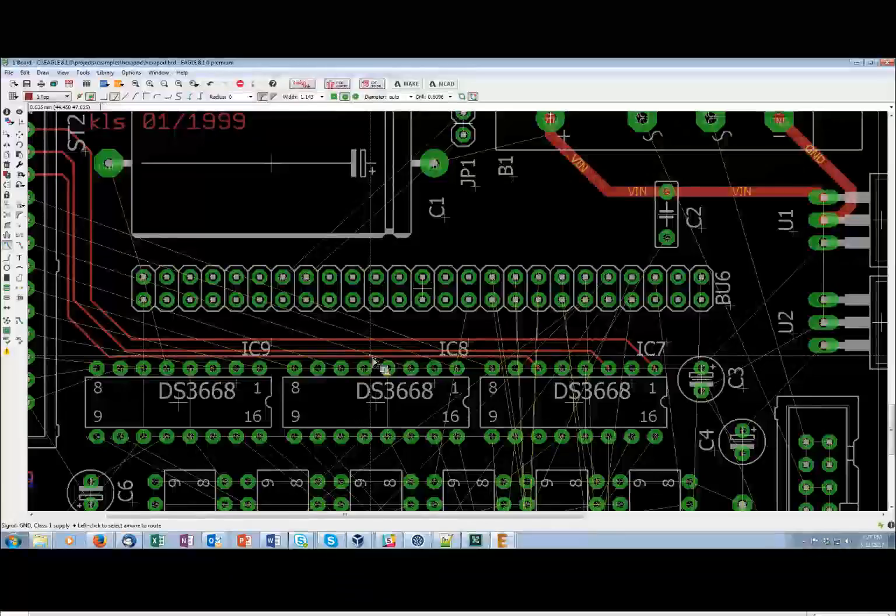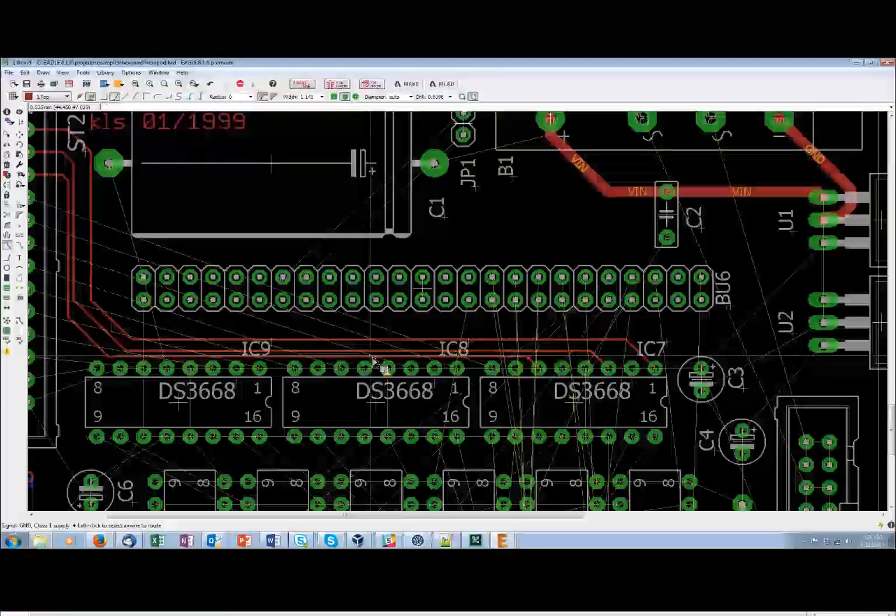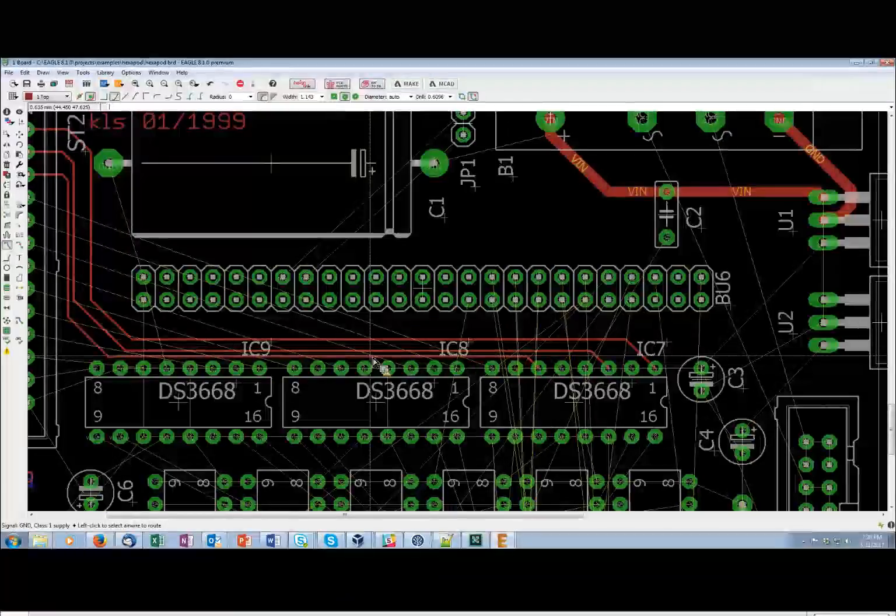Look at how quickly that square wave transitions. If you're talking of a few nanoseconds, that's a high-speed signal. And now you have to start treating it as a transmission line and taking into account transmission line theory, electromagnetics. So those are some of the main factors you want to have involved.